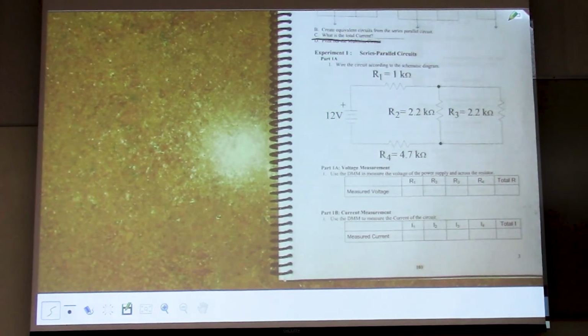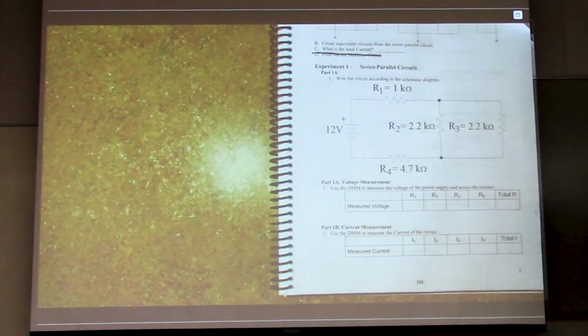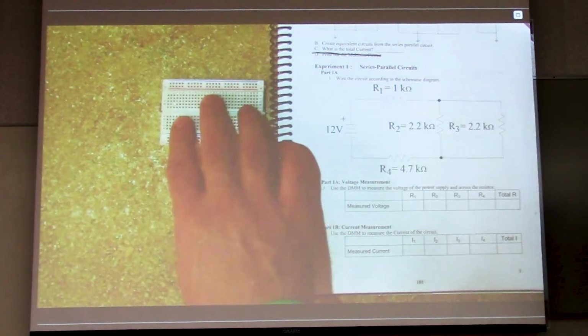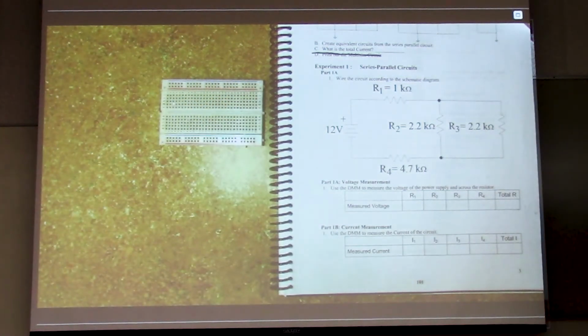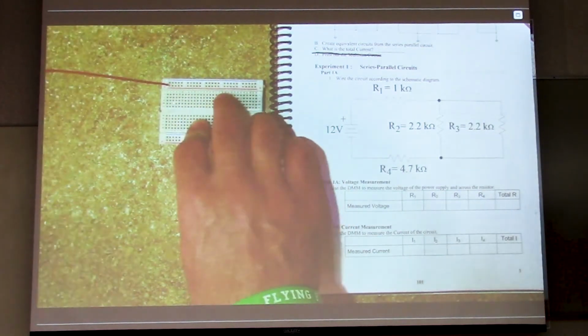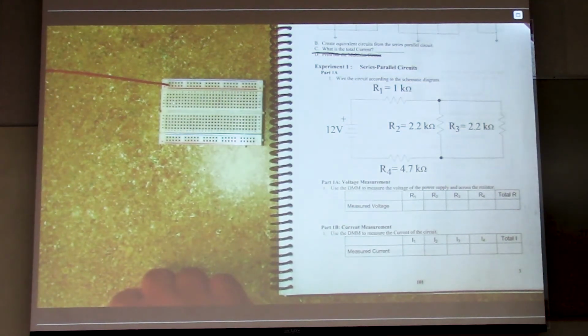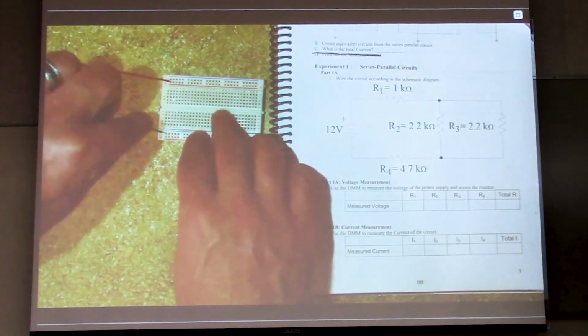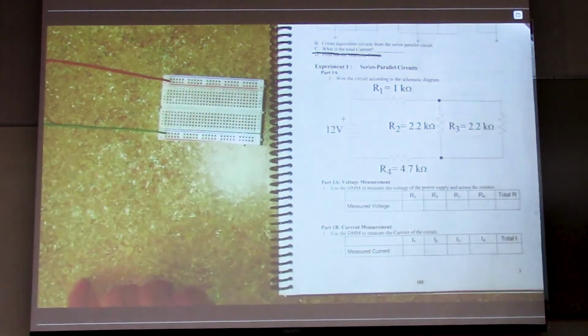So the hands-on part of the lab asks us to start by building a circuit like this. So this is going to be a circuit in a breadboard. We're going to start off with 12 volts of power moving from the left-hand side here. I like to use the top and bottom long rails of the board for my power. So I'll apply the positive side of my voltage supply there, and the negative supply to the bottom rail here. Okay? So now I've got my power attached.